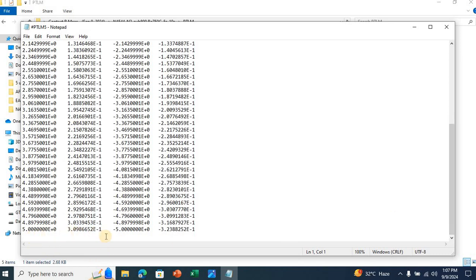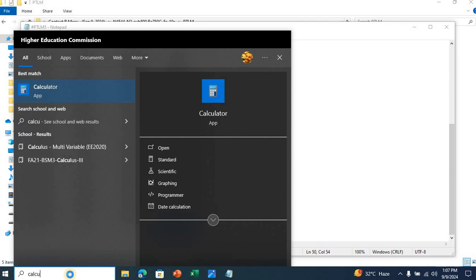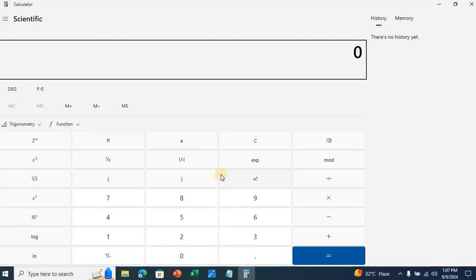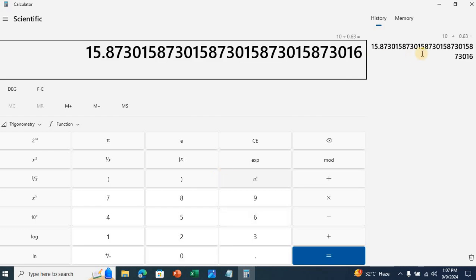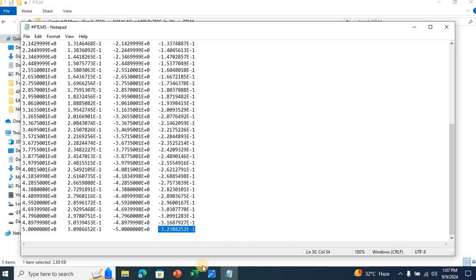and here the change in voltage once again is 10 volts. The current at plus 5 is 0.31 and at minus 5 is 0.32. So 0.31 plus 0.32 is equal to 0.63. Now my resistance is going to be 10 divided by 0.63, so approximately 16 ohms.